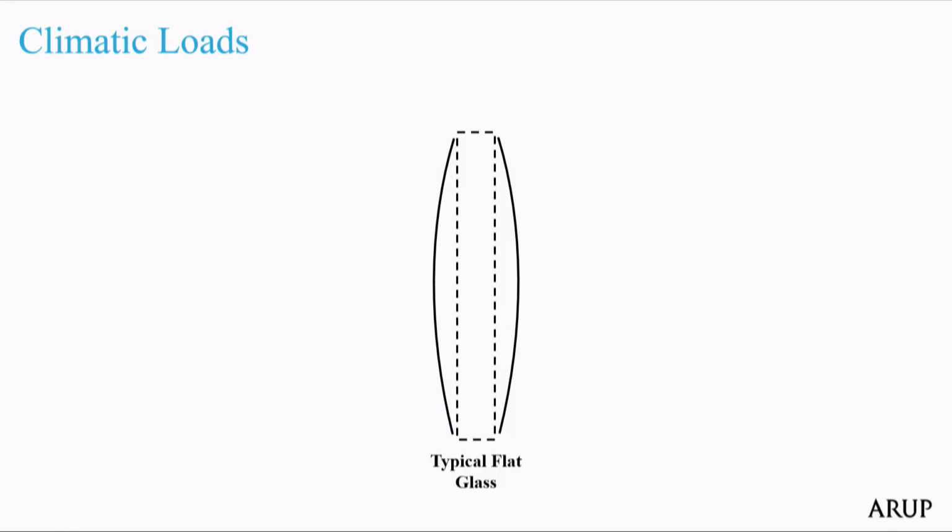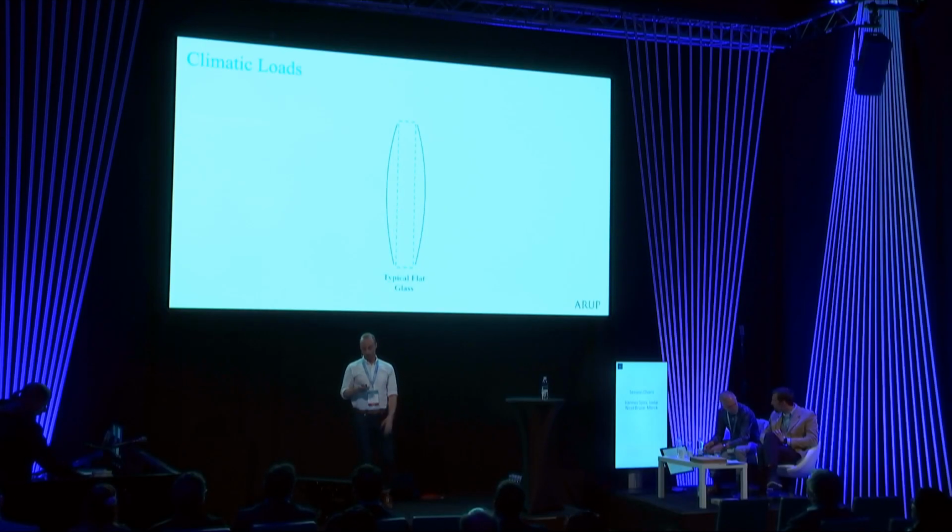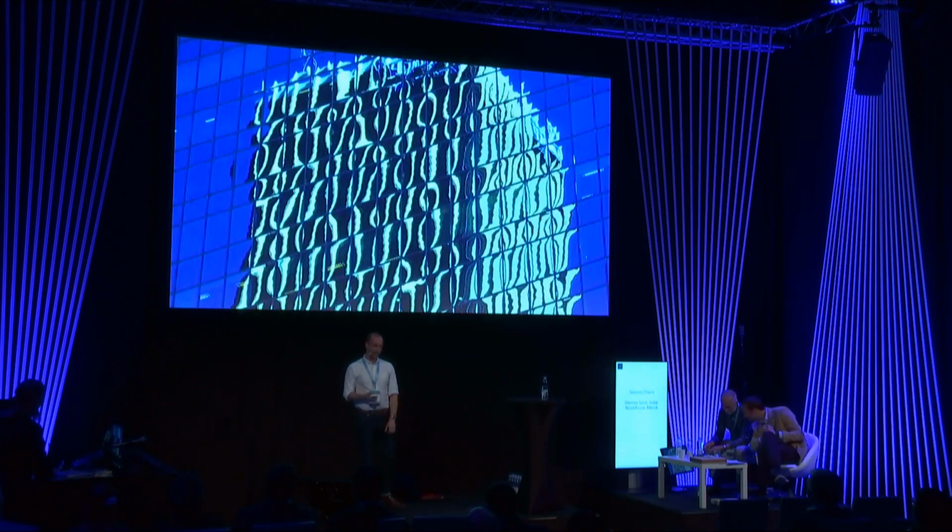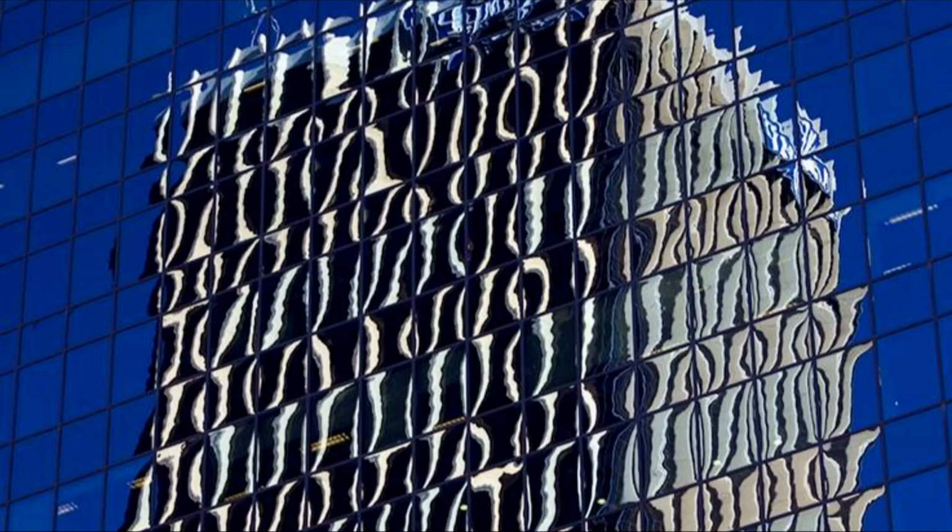And so for typical flat glass and sort of the 1-inch glass that is common in the United States, this variation in pressure causes the glass to bow out or pillow. And the consequence of that is rarely structural. It's unlikely to break the glass, but it can cause these issues, which is known as pillowing, where you can visually see a lot of these deflections, particularly with highly reflective glass units, and in an urban setting where it's reflecting quite rectilinear objects, it can really be sometimes disturbing.